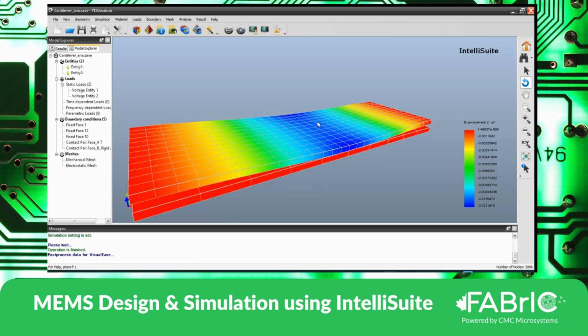And regarding the question, would you please also show the fringing field effect, and is it required to define the gap spacing area with a specific material? I think it's about the dielectric that goes between the two plates. It's all air. It is about the geometry that you want to add in between the two, and then define its dielectric property, and that's it.